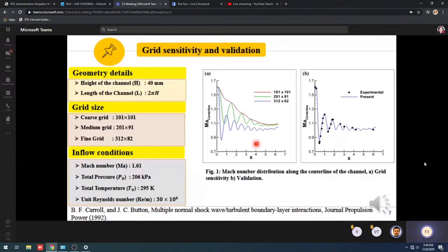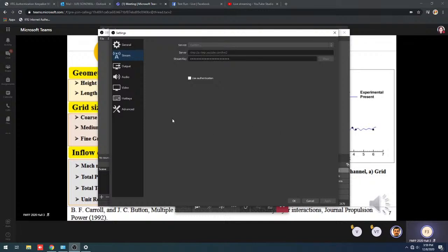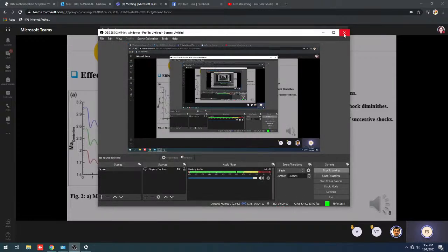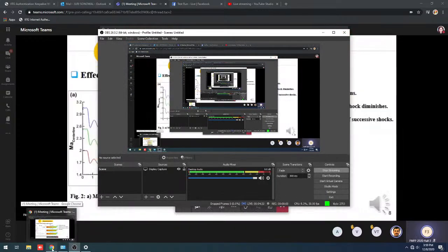Furthermore, because of the complex nature of the flow, that is, shock train formation in a channel or isolator, a stringent grid independence study may not be possible. Hence, we have restricted ourselves to the study of grid sensitivity. Here I am presenting the effect of Mach number at BPR equal to 2. Here we specify the back pressure ratio and vary the inflow Mach number to see its implications on the shock train structures.